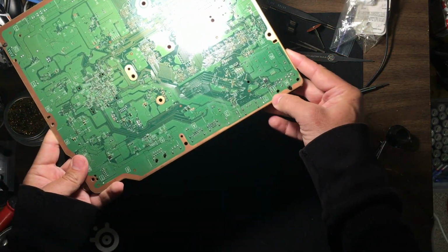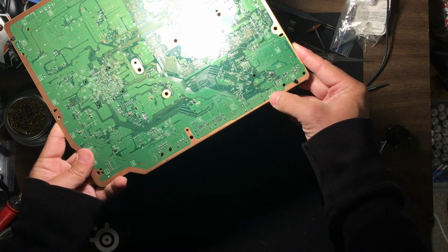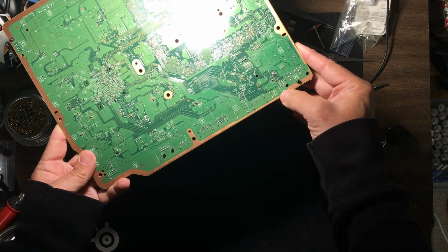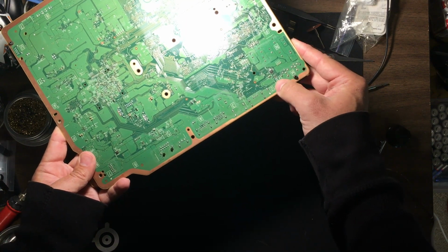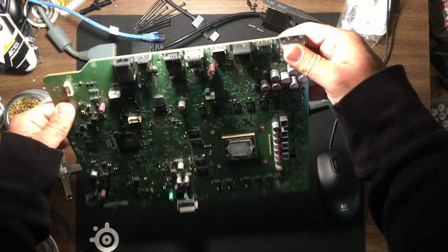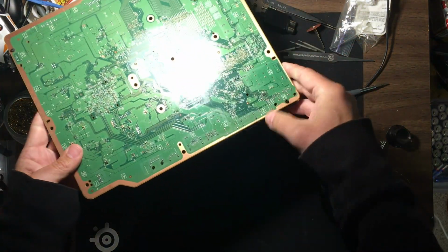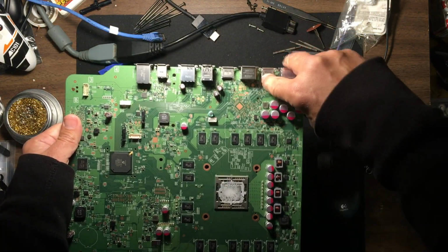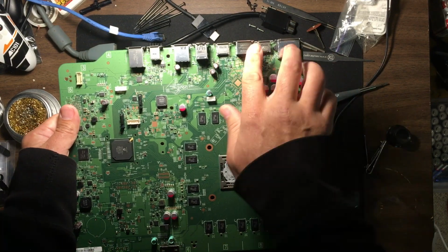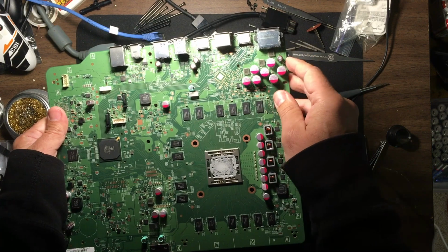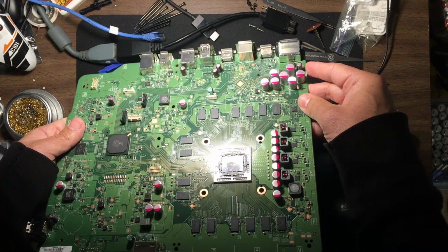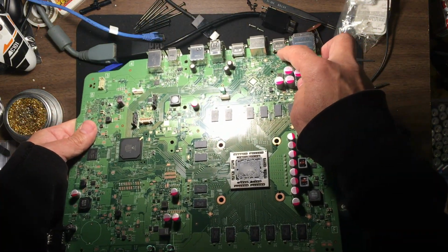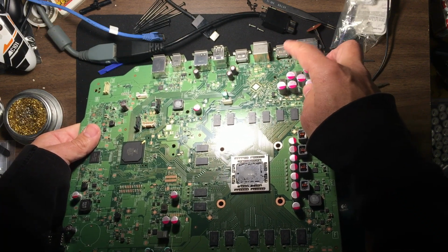But we can see here on the bottom, the main thing we're going to want to concentrate on is getting the solder out of these 4 pins here. What I think I'm going to do is put some leaded solder on here, and maybe I'll show that really quick, and then see if I can solder suck all this out. If I can't do that easily because I'm unable to get enough heat to remove that solder, I will probably switch to using a cutter, and I'm going to cut these connectors as much as possible here. Again, because of the location of these 2 ports, it makes it more difficult, but it's going to be worth a try. The main idea is to get these 4 pins separated first, and then we're going to use our low melt solder to undo those 19 pins in the back.